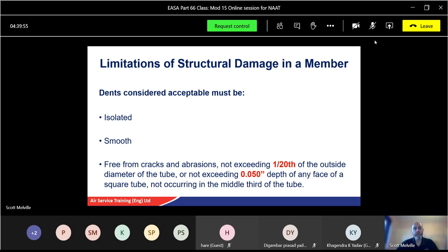Again, through experience, you'll be able to tell if that's in limits or not. Bowing: what I mean by bowing is a banana shape, where a rod should be straight but is starting to get a bit of bend on it. Using a straight edge and feeler gauges will show up any distortion. A stretched length of thread, feeler gauges, or a 3-point trammel can also be used. There are lots of different methods. Your maintenance manual will describe what tools to use and what the limits are.